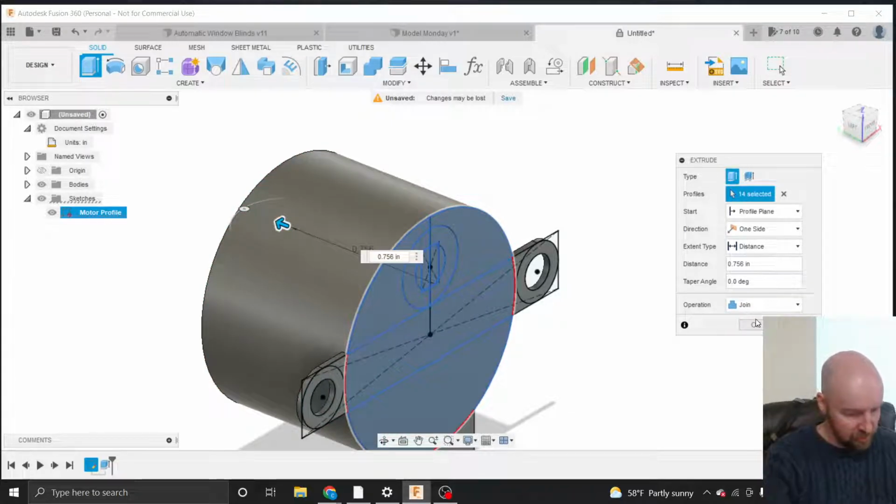And if you wanted to get real particular about it, 0.109, you could put the smallest taper ever, because this motor is indeed tapered. It's tapered 0.01 over its entire length.